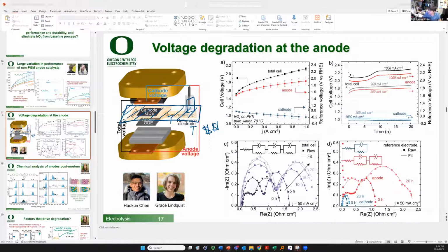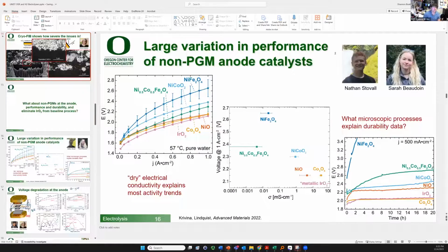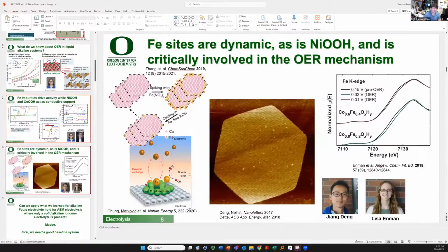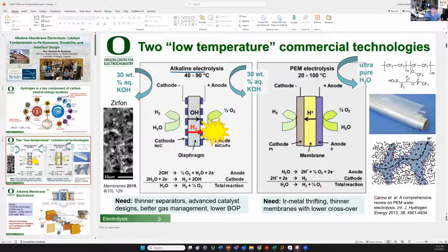It says AM research is mainly focused on zero gap alkaline research. That's the question. I would say, it depends how we define that. But zero gap, you'll hear this a lot, zero gap. What this is referring to is actually this sort of cell here, liquid alkaline. So in the old days, some cells are made this way. They had an anode, a cathode, and a separator, and there was a gap here between the electrode and the separator. And that gap has some IR loss.